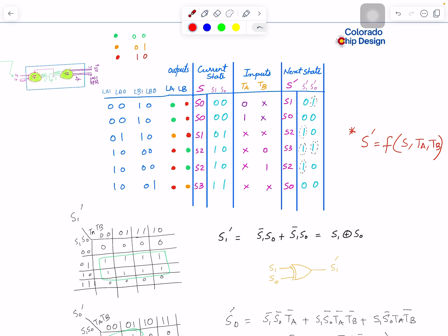So S1, S0, we go with 0 0, 0 1, 1 1, 1 0. Every time only 1 bit is changing, same thing here. I'm not going into too much K-map. So just fill this table based on this. So this one, whenever S1 is 0 and S0 is 1, look at this. For this combination and this combination, it doesn't matter what values we have.